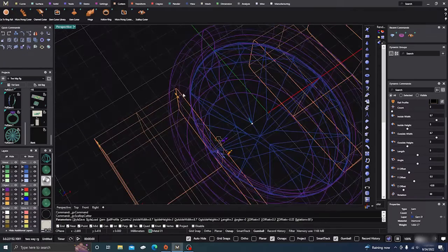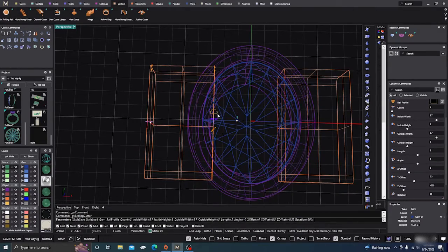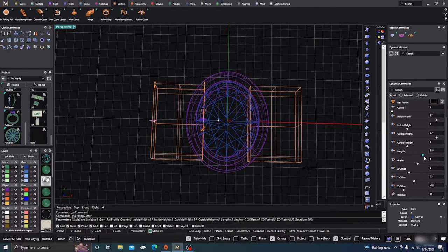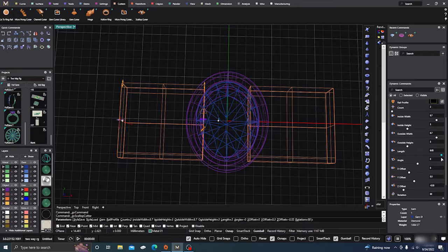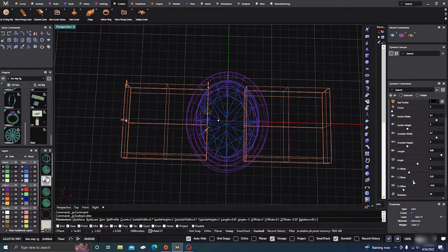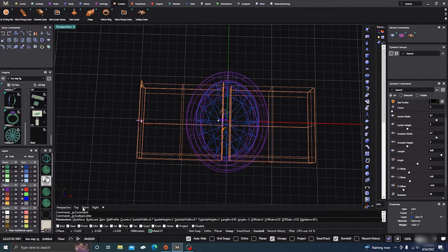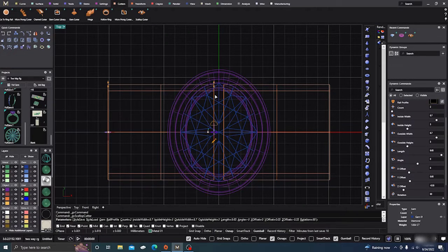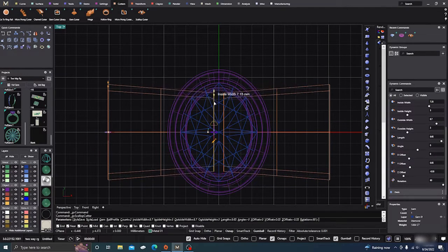Okay, it's not cutting all the way into our bezel there, so we're going to have to do some length off adjustments. So we'll just drag it out, nice long. And then we'll go to, I think it's our Y offset, and we'll drag it in. And take a look at it from the top here in wireframe. And as you can see right here, it's cutting into our bezel, so we don't want that. We just want it to cut into our shape of the inside stone. So we're going to have to drag these down a little bit.